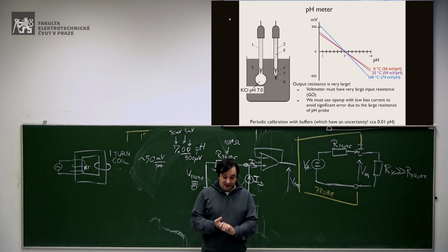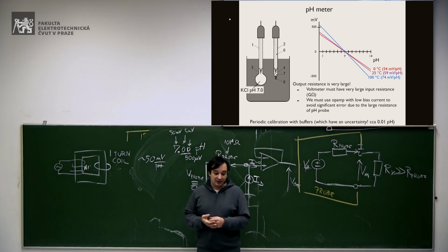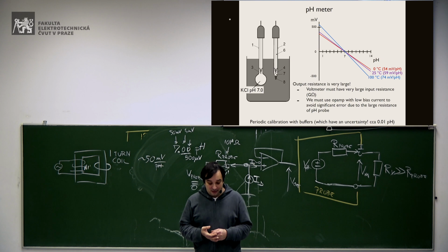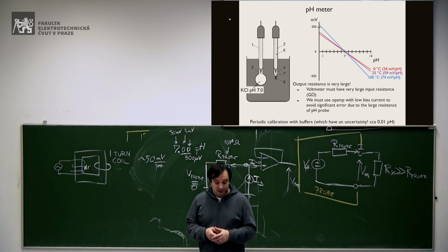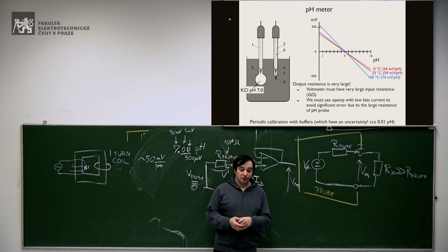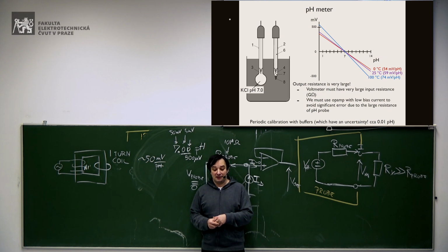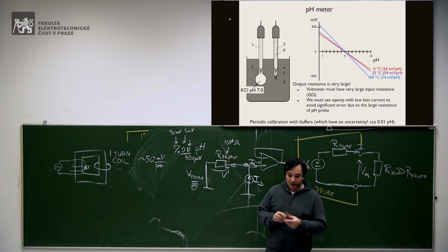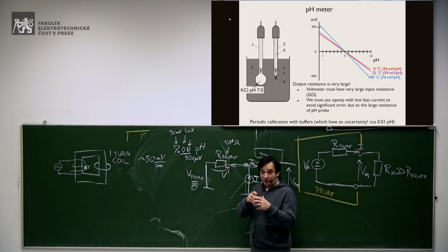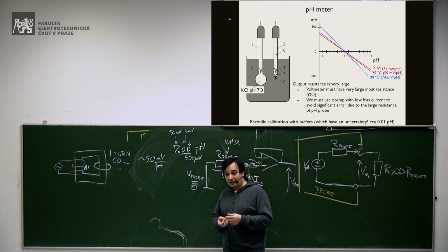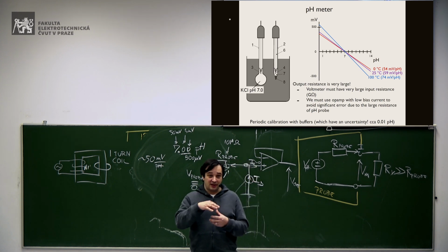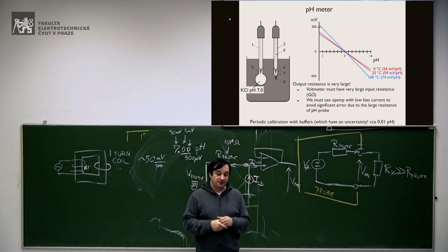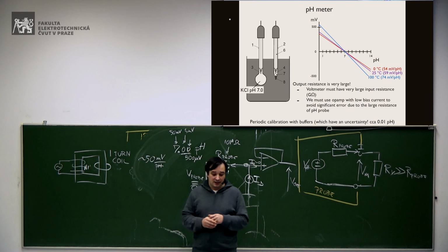By the way, this probe has to be changed quite often, because they leak out some solution, and you must always be careful how you treat it. The membrane is porous to attract the hydrogen ion, so you must always keep it wet in some solution and all this sort of jazz.